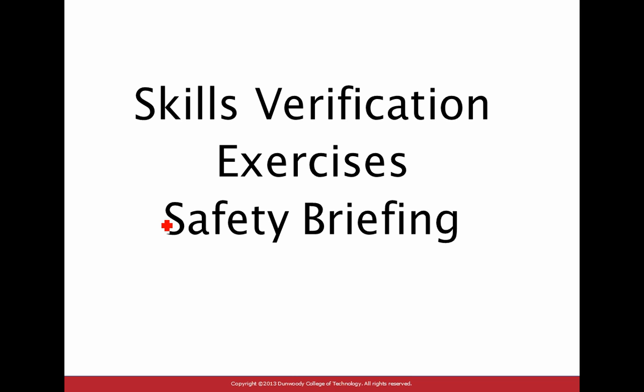Did you guys find that line? Right, almost in the middle, it says work on energized electrical conductors and circuit parts, including voltage testing. Did you find that? Okay, now that's exactly what the language is. Now go across and you see hazard risk what? 1, thank you. Rubber insulating gloves. Do you need them? Does it say yes? Yes. How about insulated and insulating hand tools? Okay, does that make sense? Now, what category would that be?